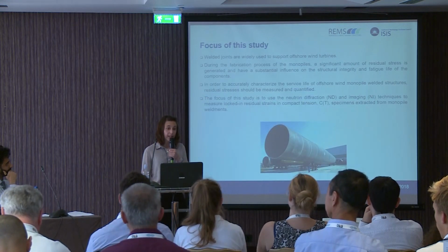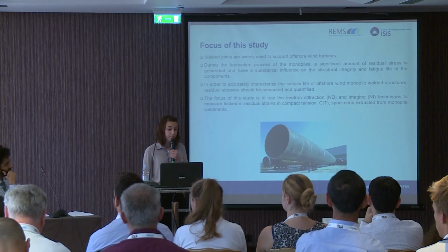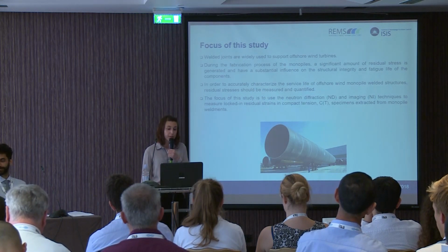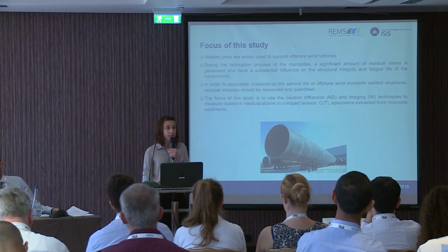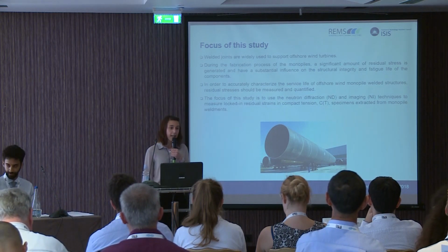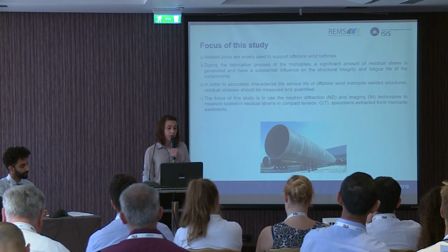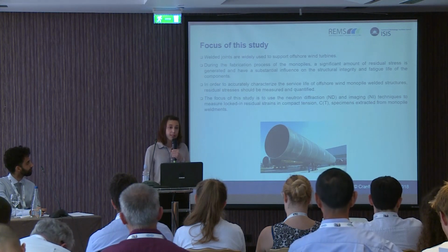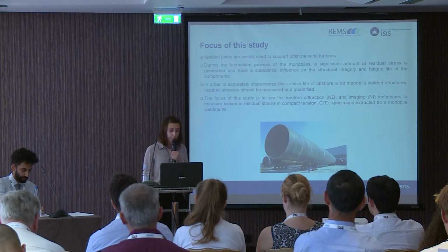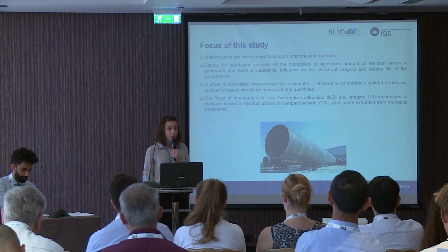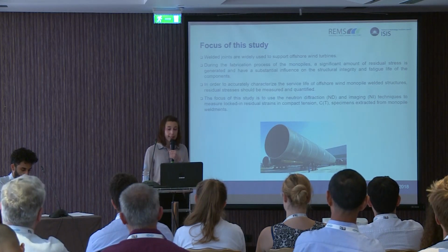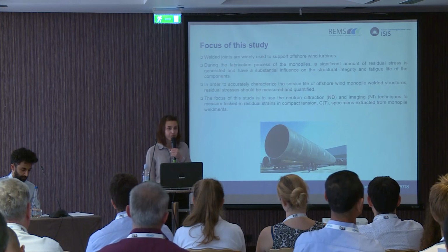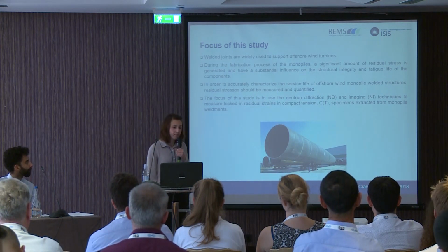So welded joints are widely used to support offshore wind turbines, and during the fabrication process of the monopiles, a significant amount of residual stresses is generated and have a substantial influence on the structural integrity and fatigue life of the components. In order to accurately characterize the service life of the monopiles, residual stresses should be measured and quantified. So the focus of this study is to use the neutron diffraction and neutron imaging techniques to measure the locked-in residual strain in compact tension specimen extracted from monopile weldments.